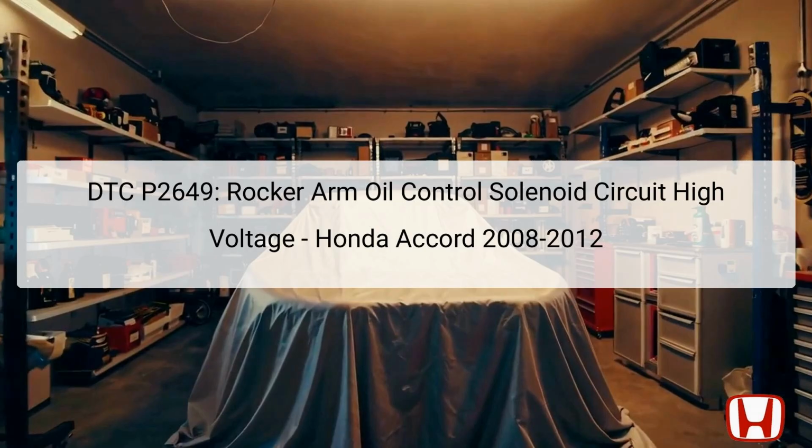This solenoid helps in adjusting valve timing through variable valve timing (VVT) mechanisms. It is located along the engine, often near the valve cover, and connects to the engine control module (ECM) or powertrain control module (PCM) via a 2P connector. When high voltage is detected in this circuit, it may lead to performance issues, increased emissions, or potential engine damage if left unaddressed. Therefore, proper troubleshooting is essential to diagnose and rectify the issue, ensuring the vehicle operates smoothly.